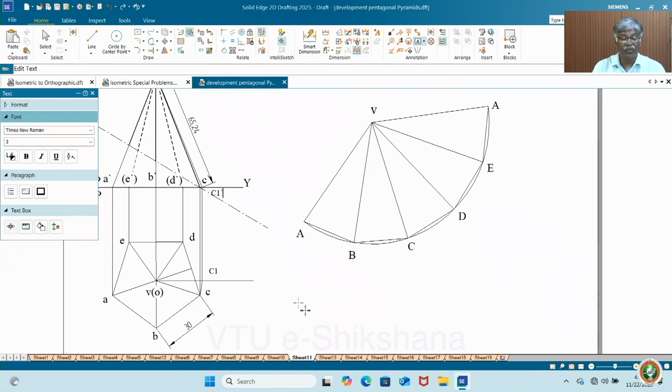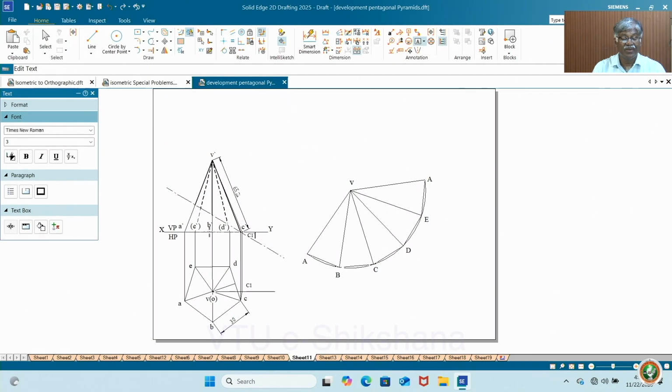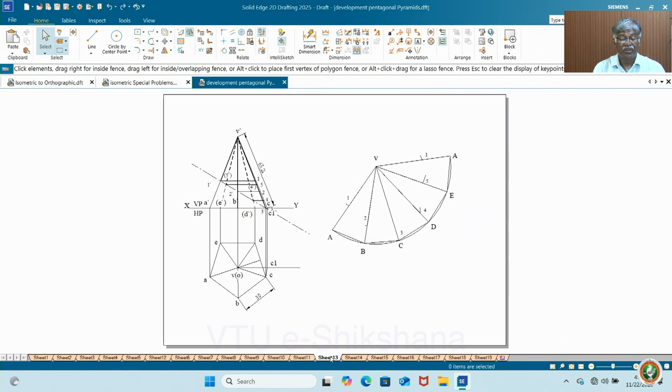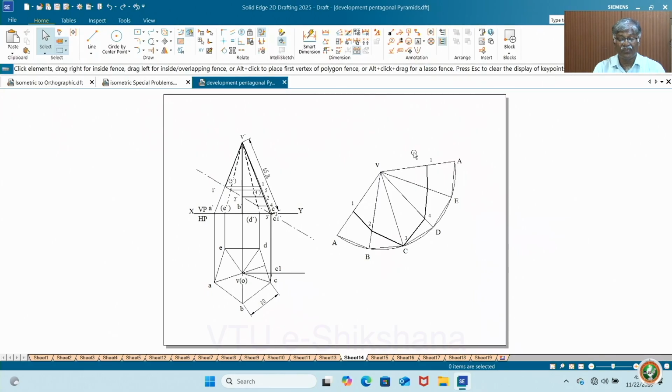Now after doing this, you take the intersection points. You just observe here, I have darkened the portion containing the apex. That is the requirement, dark the portion containing the apex, because they need the development portion containing the apex. So definitely you have to do it like this, dark the portion, okay. That is why I have not put an arrow here. So you can just draw a line, in fact, in that case, okay. Now name the points of intersection, identify this, then get the profile.